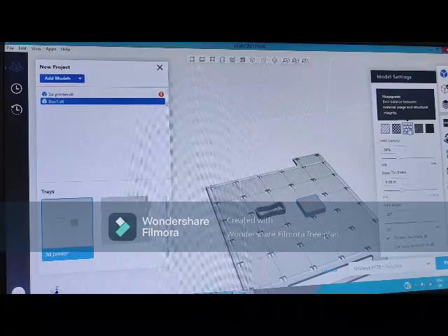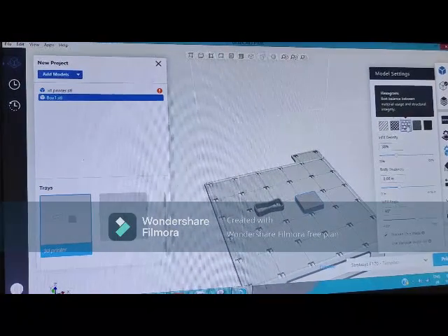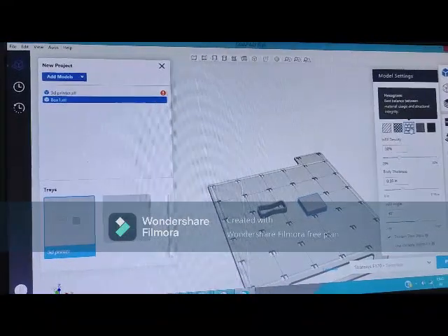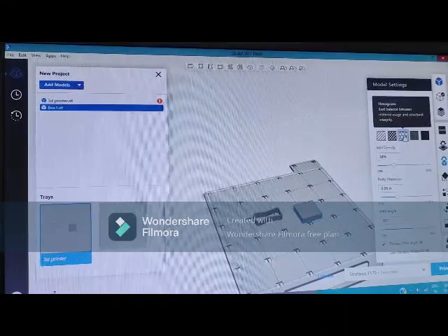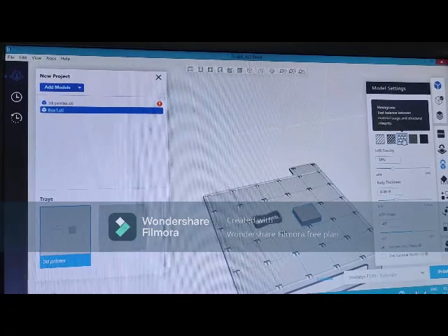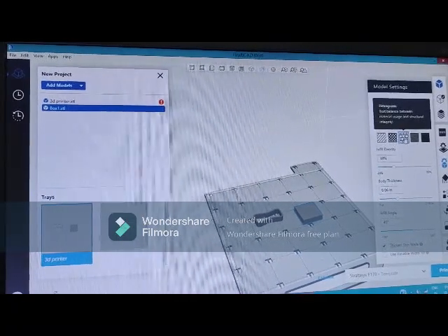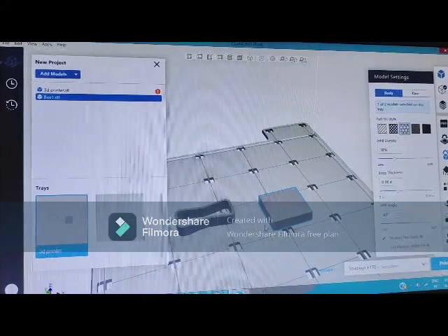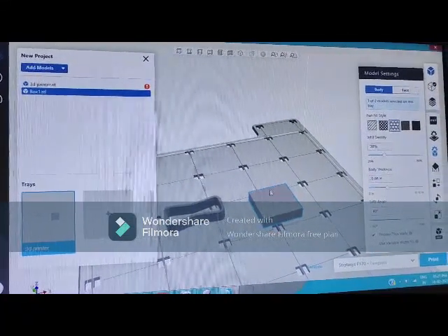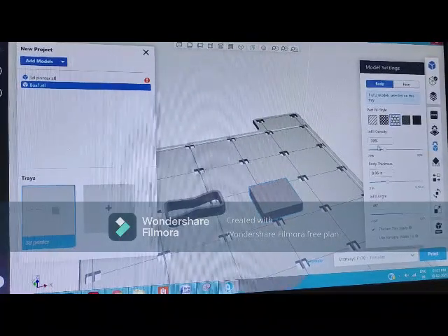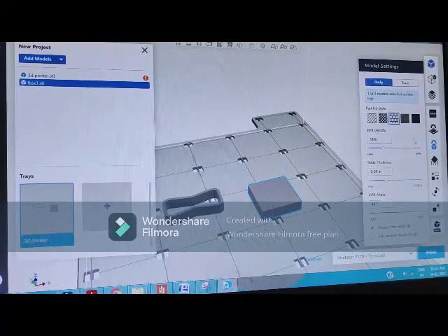Infill means how much amount of material will be printed on a particular model. Like I need 50% of the material. That does not mean that it will print half. It will complete the material. Suppose here we have a rectangular box, so it will complete the rectangular box, no doubt. About the density or the infill, how much it is going to fill, depends on this one. 38% I'm filling this one.